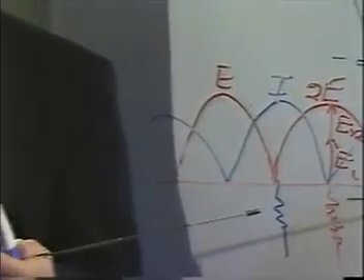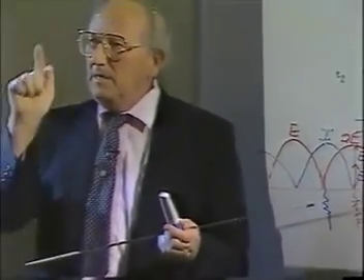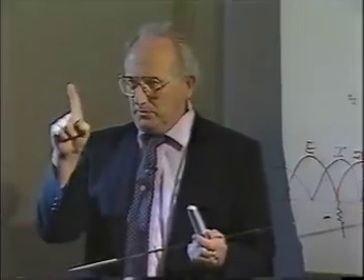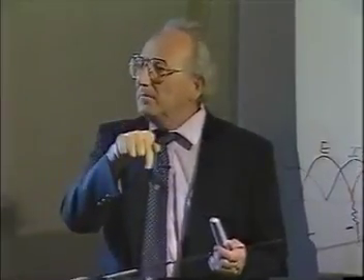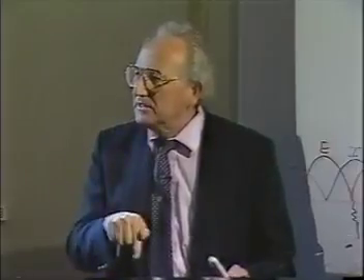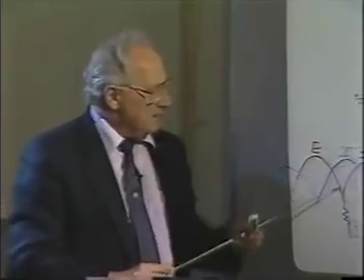You will have an E max and an E min. At E max, you know that the impedance is always greater than Z0. It's a pure resistance. You know at Z minimum and E minimum, you always have a pure resistance that is less than Z0. And it's established that when the current is maximum, what's the voltage?